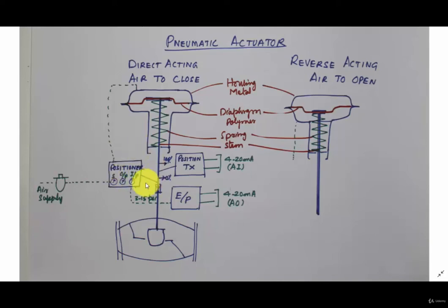So this is required for the process industry, especially high pressure pipelines like gas wells, where there is a huge process pressure. Against this pressure, the valve has to operate. So we need a positioner. The positioner will have small gauges showing the supply pressure. Every pneumatic instrument requires air supply. This air supply it receives from the air header or air storage vessel.